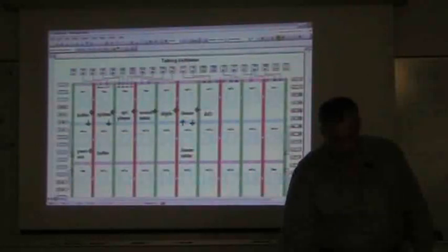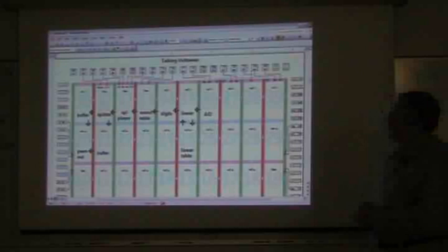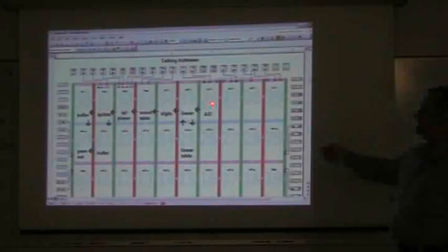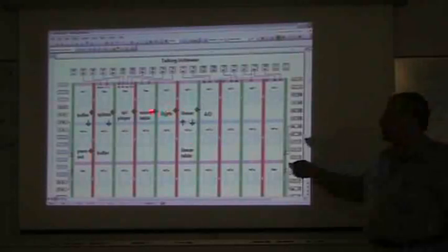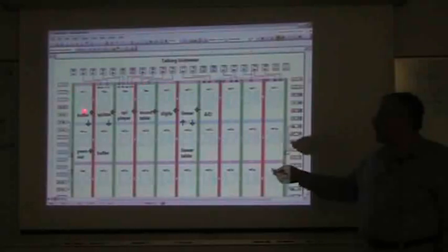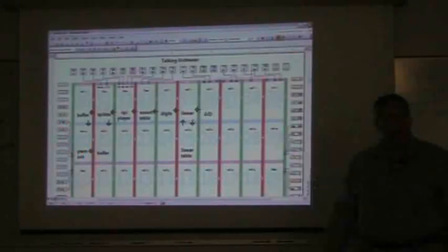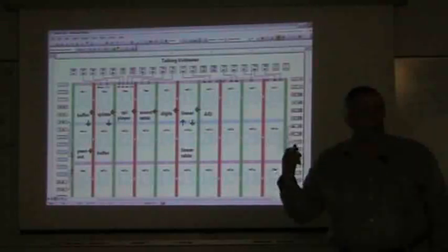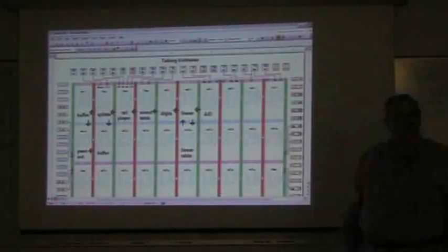Here's a picture of it laid out on S40. This node is just taking samples and subtracting and getting a difference, giving the difference to this node, which looks it up in a table and linearizes it. This node splits out digits. This node turns the digits into the appropriate address and length of the data in SPI. The SPI plays it using these 4 pins talking to an SPI chip. It comes out of there, and it goes into one of these 2 buffers. It comes out of the buffer, and it goes to this node, which pulse width modulates it, and it goes out on a pin. And if you put a speaker or an earphone on that pin and twist the potentiometer on the A to D, you hear it speaking out the voltage on the device.